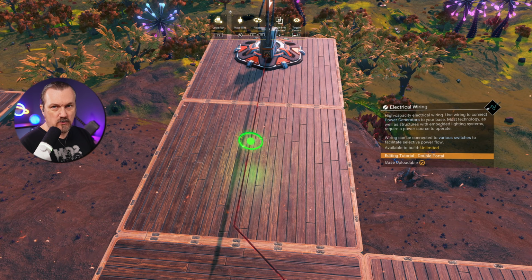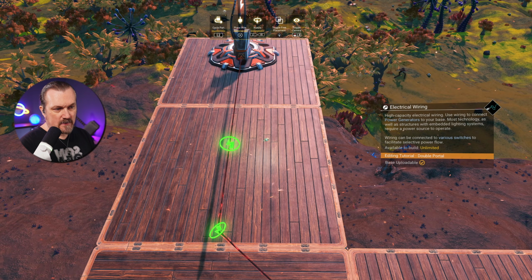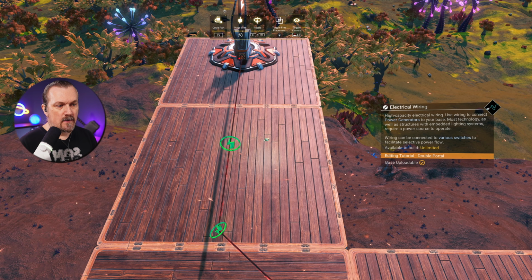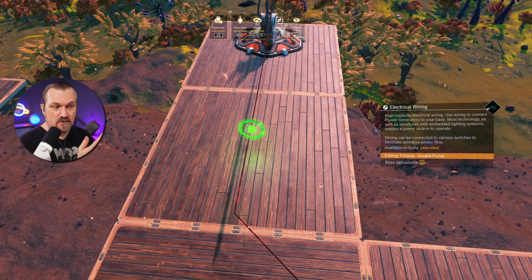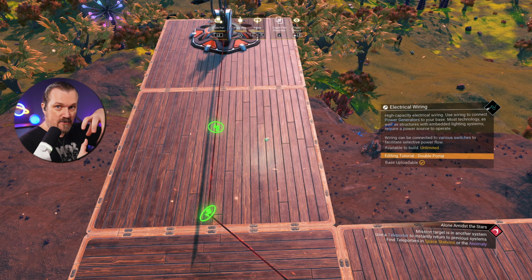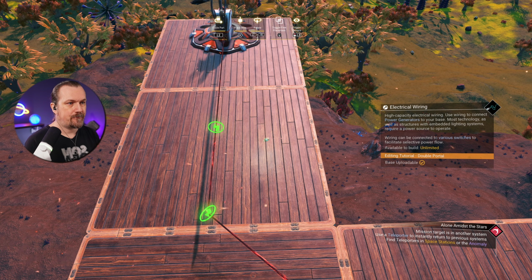So if I snap to it and I press rotate, you can see that it does a little bit of a flip, and then you can see that the connector is now rotated. And that's because I'm following the wire further away from me. So I can just keep rotating and either snap or glitch upwards, then rotate and glitch downwards. And that's how you, for example, can glitch two things upside down, like mirrored on top of each other.